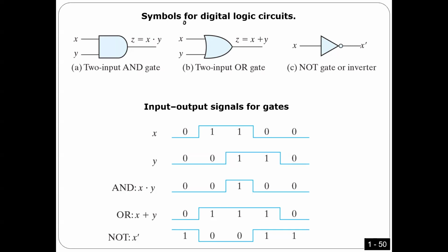So for OR gates, if one input is 1, I don't even need to look at the other inputs. The output is directly 1. It's enough to have one input that is 1. If possible, that's more than what I need, because it's OR. This is how it works. So let's do the truth table of this one.